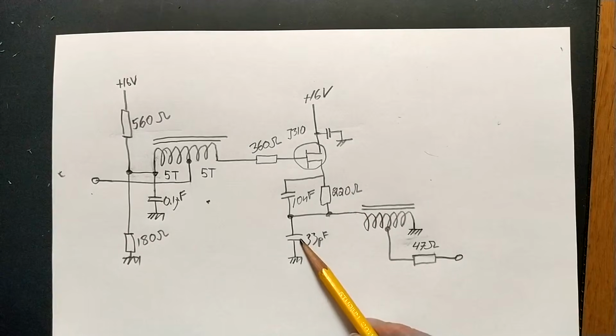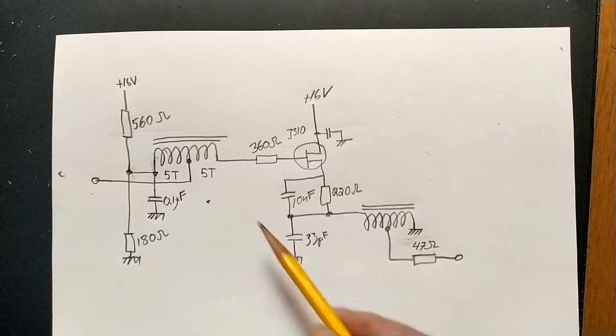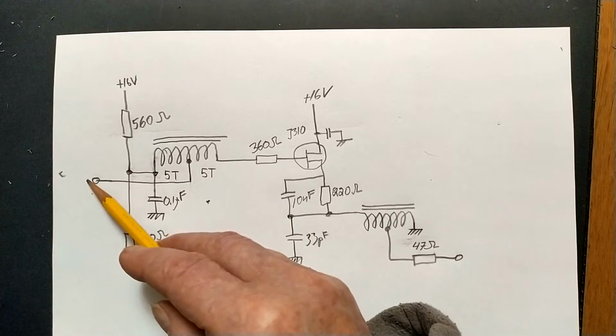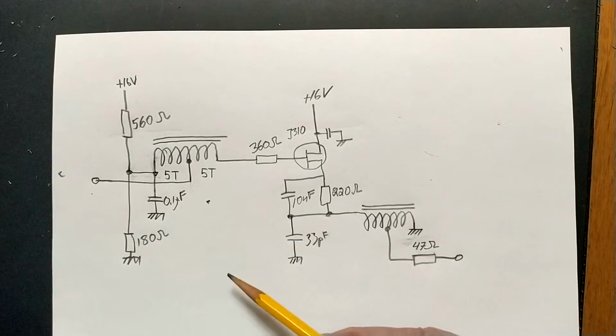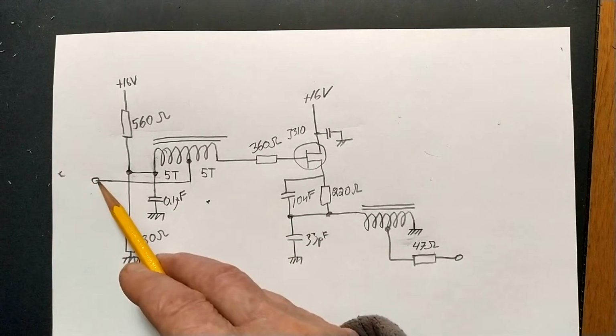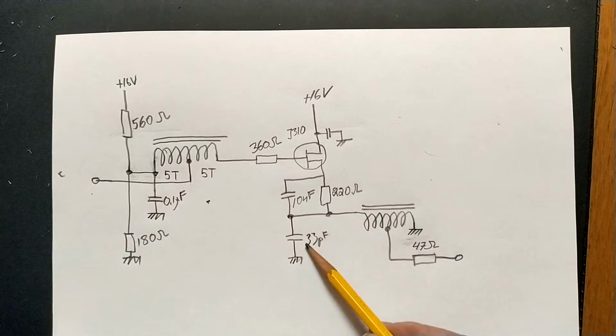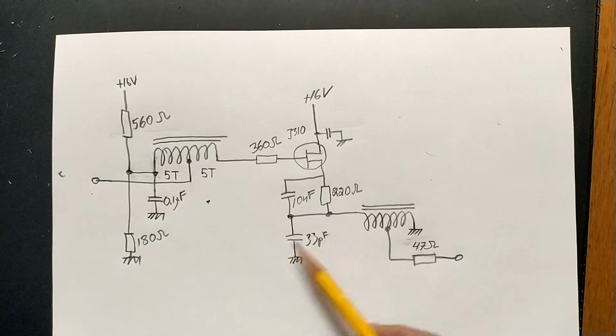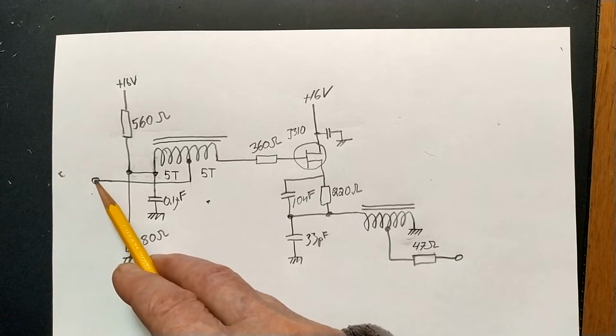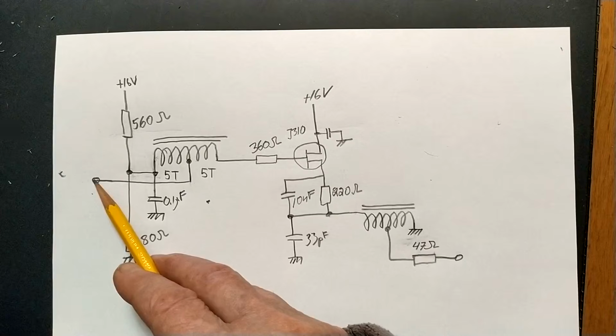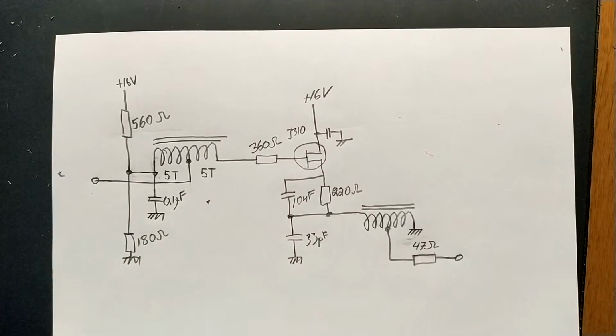This capacitor is selected to give the same crystal current and Q for the filter as when I have this not connected at all. So it means that the impedance is maximized. If I make this capacitor bigger, I get the negative resistance at this point and the Q increases, and that's not what I want. I think that generates noise. Anyway, this is what I am running at the moment.